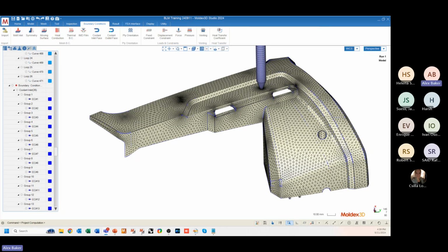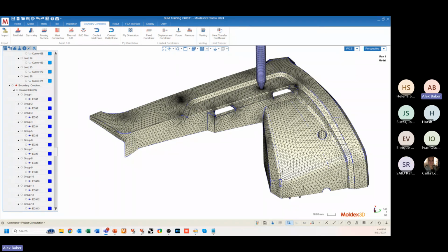Can we characterize both base material and colorant? Whenever we characterize a specific grade of material, we characterize it as a complete matrix. We do not characterize the different additives separately. We characterize them all as the mixture that you would experience in the molding process.